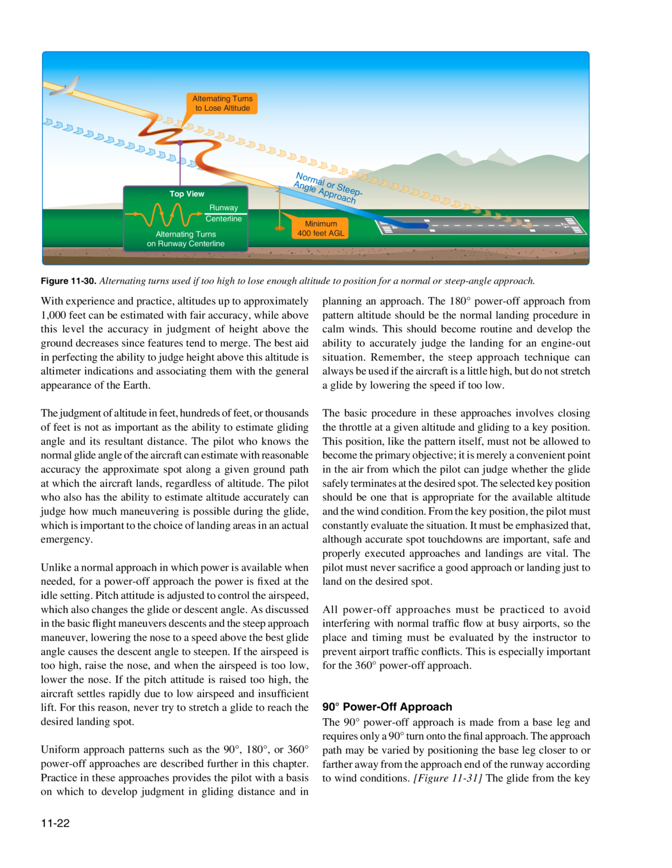All power-off approaches must be practiced to avoid interfering with normal traffic flow at busy airports, so the place and timing must be evaluated by the instructor to prevent airport traffic conflicts. This is especially important for the 360 degrees power-off approach.